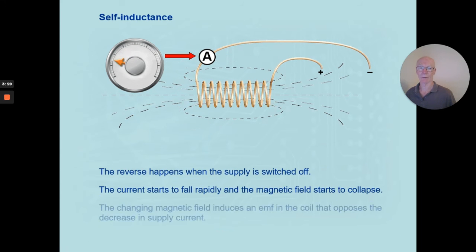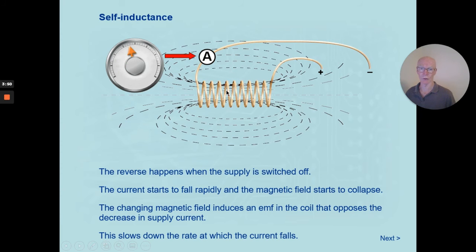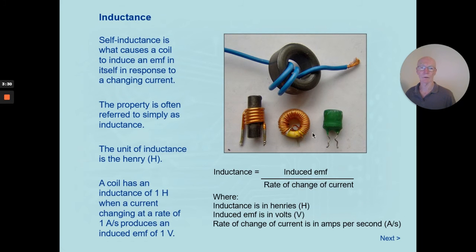And a similar thing happens when we turn an inductor off. The magnetic field collapses, and all of that energy that was stored in it now gets returned to the coil, cutting through the conductors, reintroducing an EMF in the opposite direction, slowing down the change in current. So once again, when the current is turned off, it doesn't instantly fall to zero, it slows down over a period of time. An inductor can be as simple as 1 or 2 turns of copper wire, or many turns,